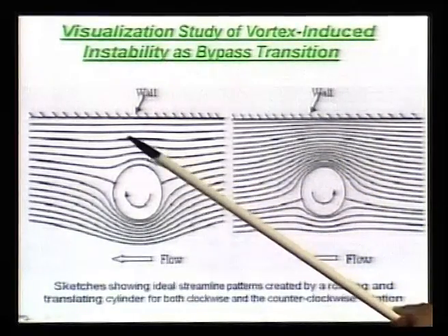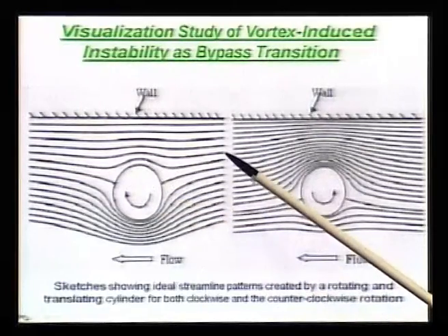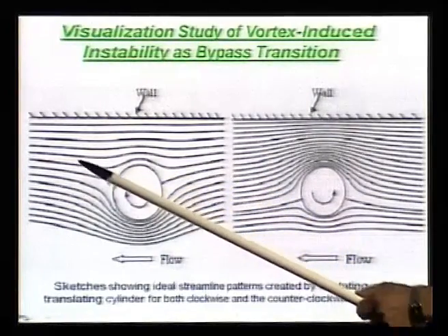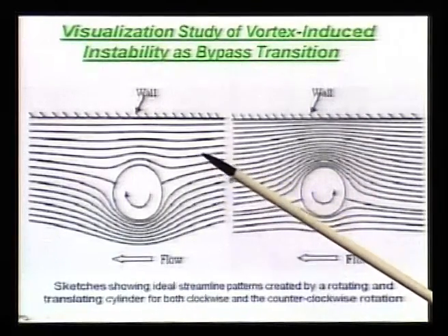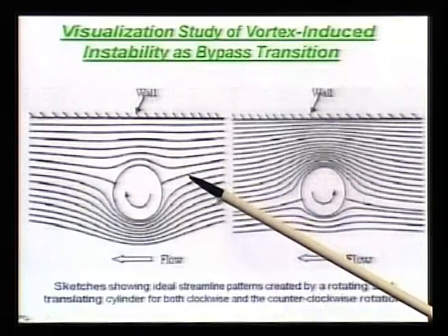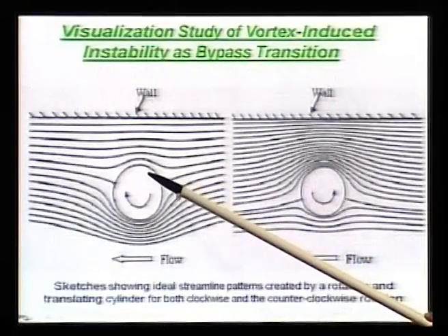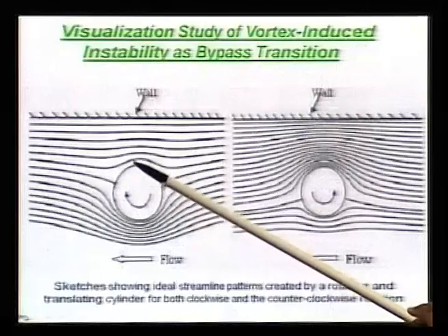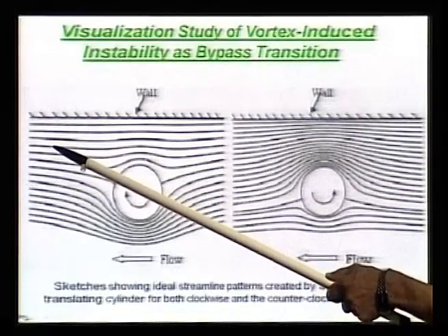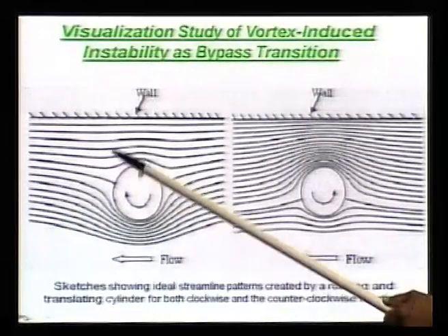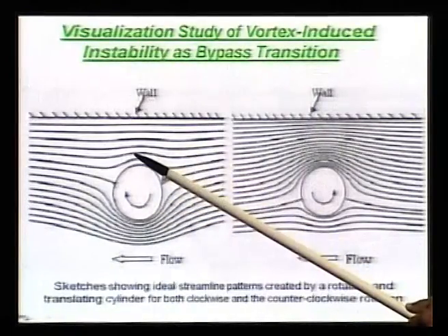That is given by the streamline curvature. And here you see a very interesting feature. You start off with the adverse pressure gradient, but more or less with a similar divergence, that is followed by a favorable pressure gradient, again followed by a rapid adverse pressure gradient, and again followed by favorable pressure gradient. So, whatever damage that can occur only here.